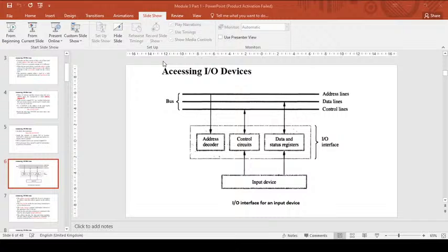Now, Testbit #0, STATUS. You know that to check whether data is available in the DATAIN register, that means to check whether a key is struck, you have to monitor the SIN flag. So what is the SIN flag? SIN is bit 0 of the status register. As per this example, SIN flag is bit 0 of the STATUS register, so you will be checking bit 0 of the status register, that means you are checking the SIN flag.